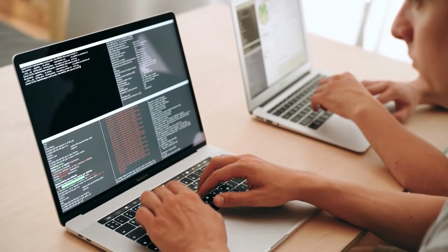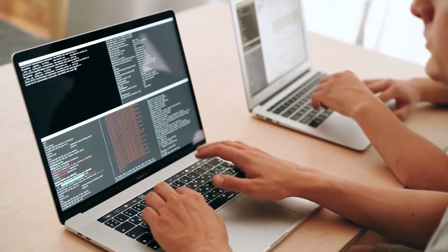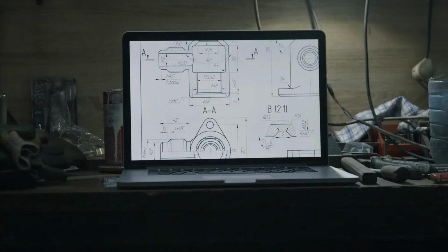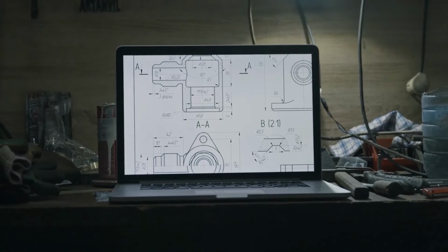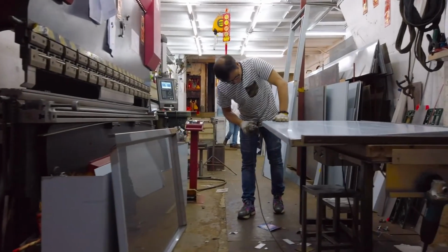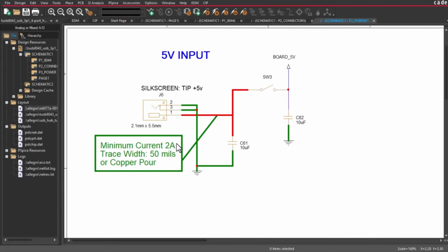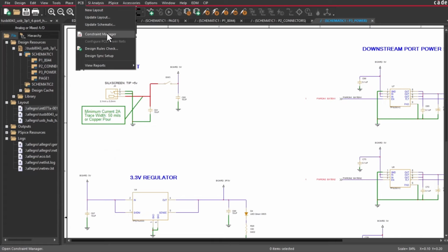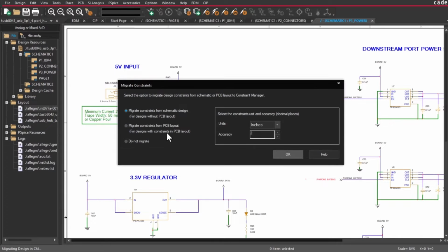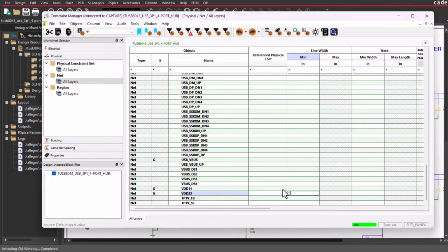So programming notes for developers, firmware notes for firmware engineers, notes for standoffs and other mechanical items for mechanical engineers, and especially notes for the design, whether it's trace widths, component placement, and spacing notes for the PCB designer. In addition, including constraints on the schematic side if the schematic capture tool can hold design constraints. And then, of course, a bill of materials and everything else that you typically do with a schematic.